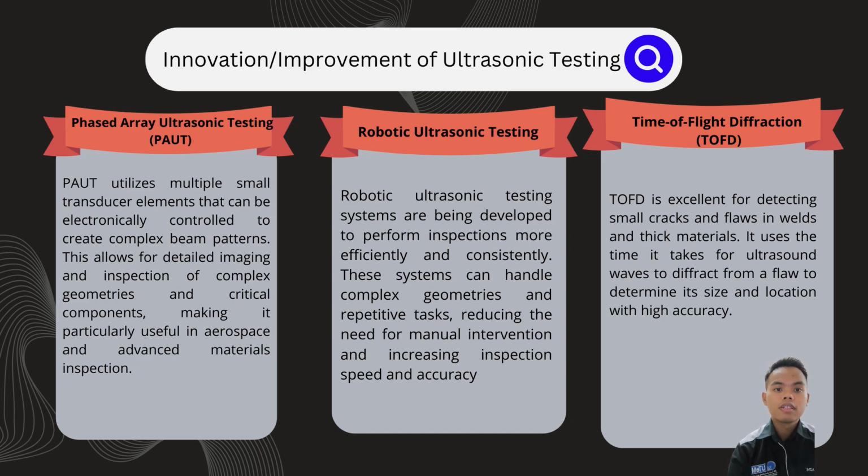And then third, time of flight diffraction, TOFD. TOFD is one of the most reliable non-destructive testing methods, working well for both pre-service and in-service inspection. There is no radiation with this method. Time of flight diffraction provides inspection data that is recorded and can be stored digitally for future reference.